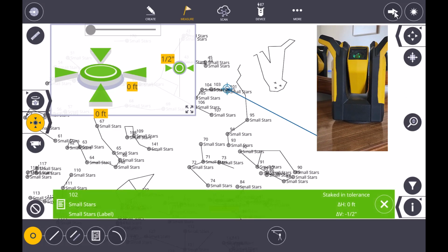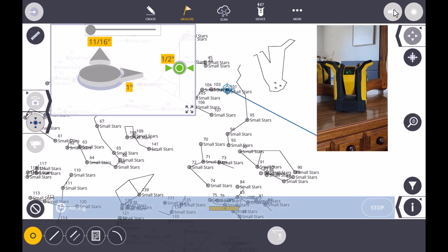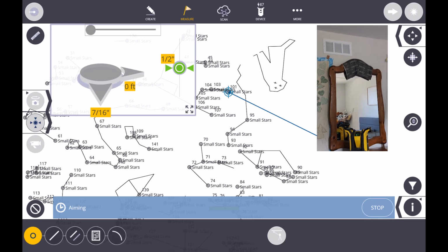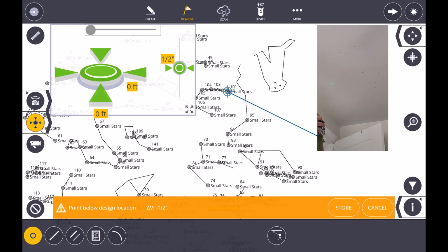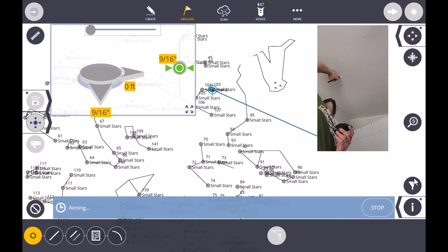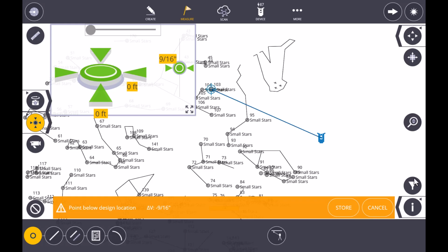You can see my drawing that I made from SketchUp, and all of the small stars are turned on right now. I have the big stars off. The small stars I laid out with a little X and the big stars with a little circle, so I know what size to put on the ceiling whenever I'm finished. And again, I'm simply using an as-built of my room using a no data setup with the robotic total station I already took. So I hit my corners as control points and immediately was able to start laying out all of these stars.